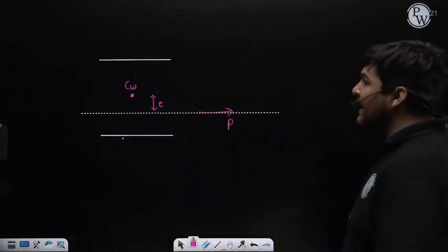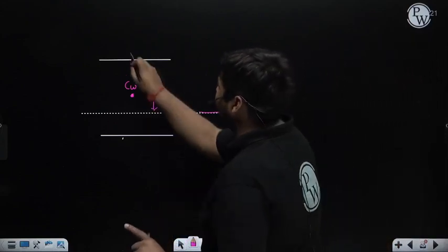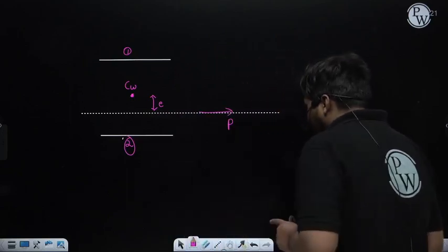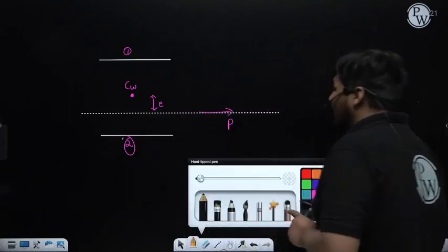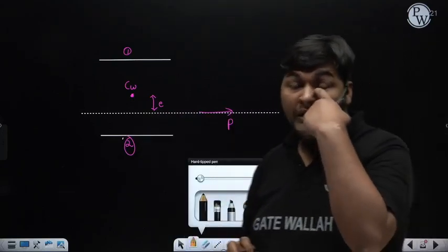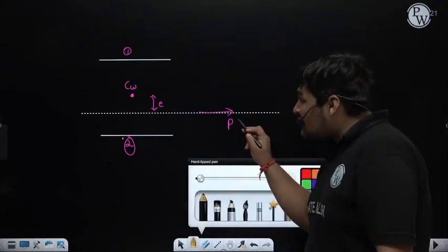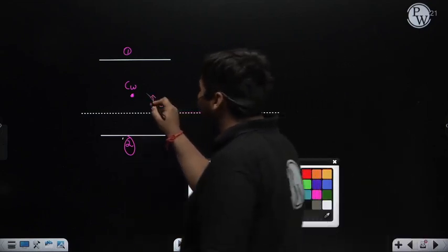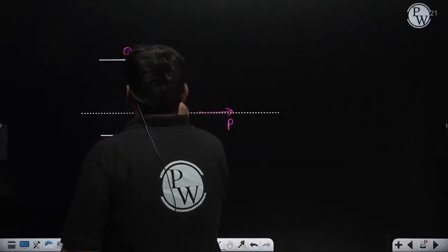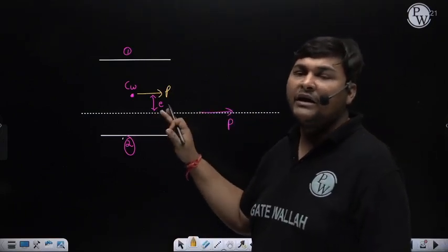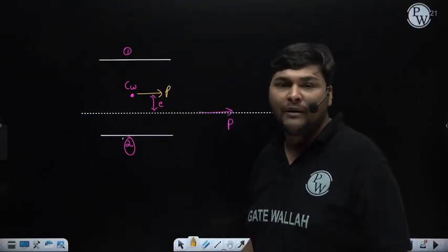Now before calculating the stress within the weld, it is weld 1, it is weld 2, and it is the combined centroid of both the welds. Now to calculate stress in the weld, first we need to transfer this force P to the combined centroid of the weld. And when you transfer this force P to the combined centroid of the weld, one direct force P will come, meaning primary stress will come. It is 100% sure, whether it is passing through the combined centroid of the weld or not.